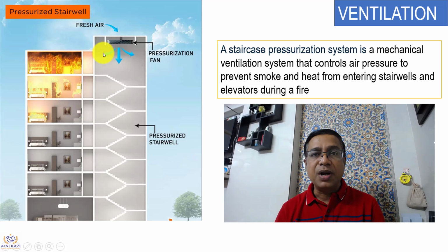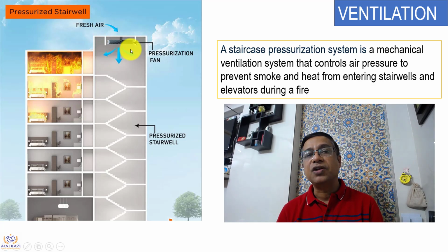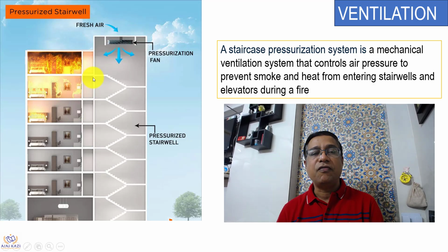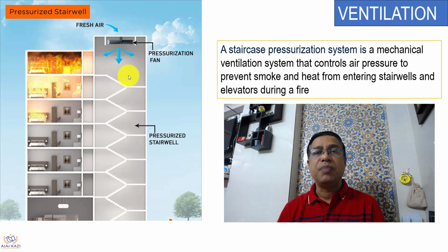But there are buildings where the staircases are internal. In some cases, some customers put in an extra effort of having forced ventilation, where we have a forced ventilation pressure fan at the top of the staircase. In case of fire, this stairwell is pressurized with air so that the fire doesn't get into the stairwell. In the Indian context, we maintain a 50 Pascal pressure difference between the zone which is under fire and the stairwell.